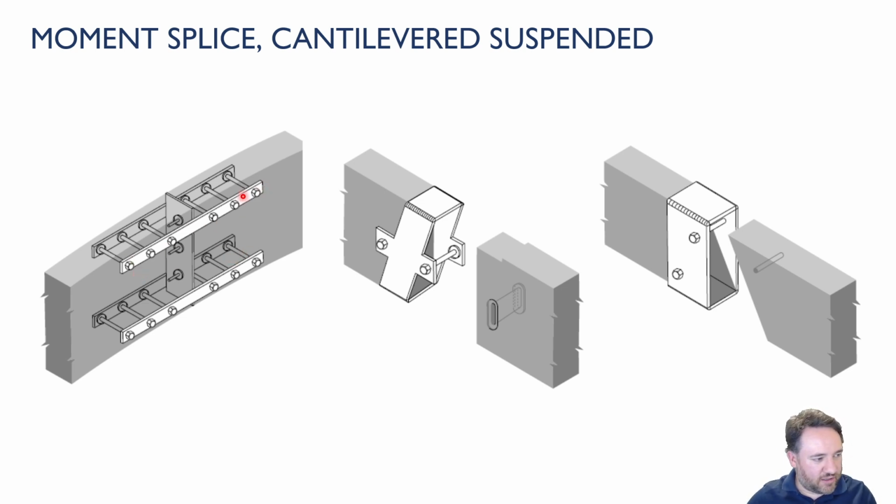So I have one set of plates on the top, one set of plates on the bottom. Now, if this wood wants to expand and contract perpendicular to grain, it's perfectly happy to do so. It just means this plate will get closer to this plate, or this plate will get further away from this plate, but there's nothing restraining that movement. Okay, here you can see there's some shear connection in the middle here that I didn't talk about. This could be, for example, shear plates.